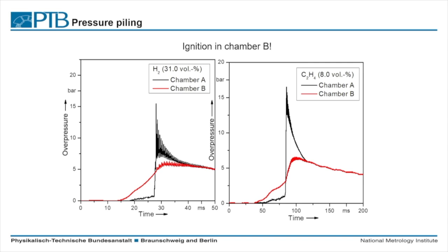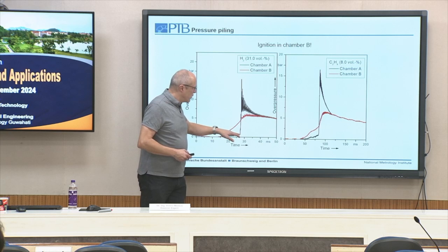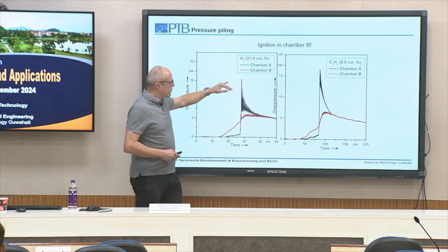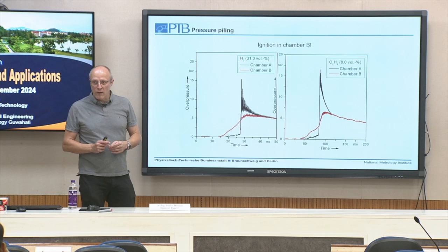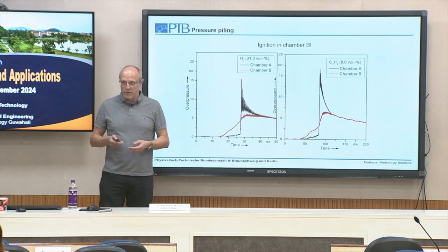That's one factor. And we do not start at 1 bar, because our flame in the first chamber led to a pressure rise, and therefore until the flame reaches the second chamber, there is a gas flow from chamber 1 to chamber 2, and we start with a higher initial pressure. So that means we have a fast pressure rise starting at higher initial pressure. For this configuration we already yield nearly 17 bar. And again, with the same configuration we also measured 35 bar.